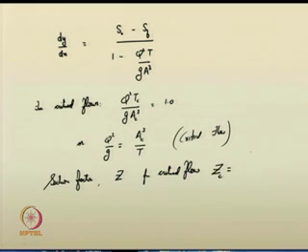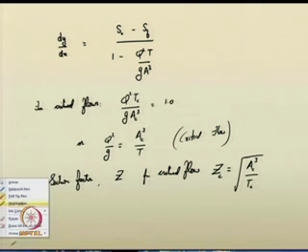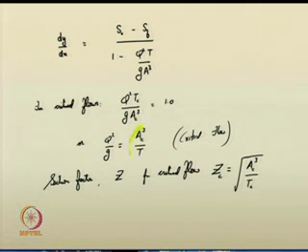This was given as the square root of Ac cube by Tc. So, in the critical flow equation, this particular right hand term is nothing but the square of your section factor, right. So, Zc was defined in those portions. So, here again you can use them.